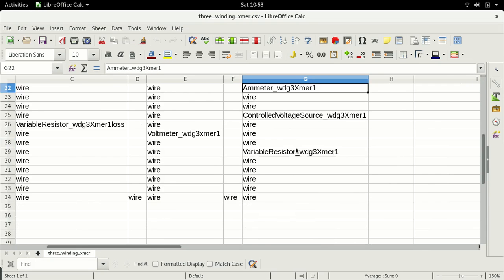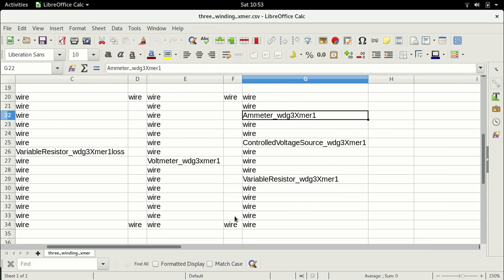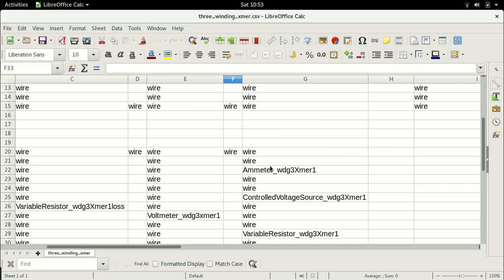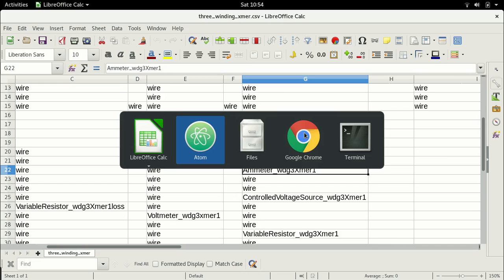Because the dot polarity of this winding is the lower terminal, this ammeter has a polarity in the upward direction, which means that the positive polarity is towards the upper terminal. This is something you can confirm on your own. So we can directly use this ammeter because it is measuring the current being fed back in the freewheel path. Let's add these.